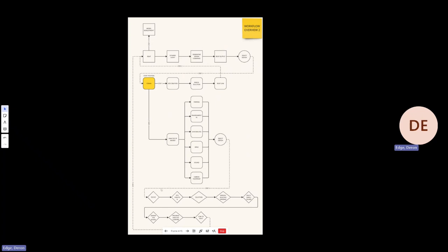From here, we'll select the design, and then the same thing goes back into TestFit. The problem here is we'll have to manually build all the masses that we've been developing in TestFit. There's no good way to link it up at the moment. But from there, we'll build it, and then we'll start doing the interior massing studies and layout studies with the masses we've developed earlier. Mostly this will function with the Multifamily Solver, not so much the grocery elements or the retail elements, or whatever elements you would have in there.